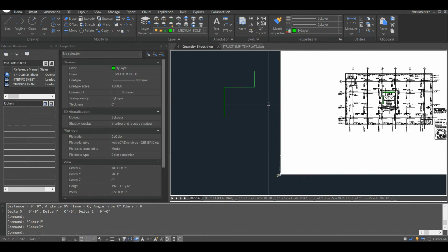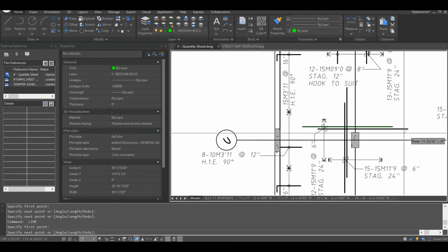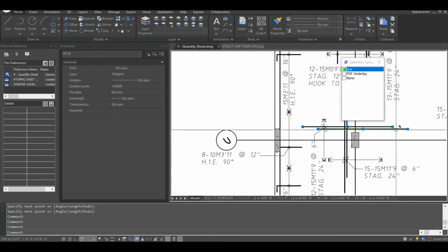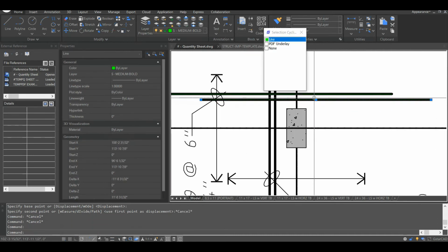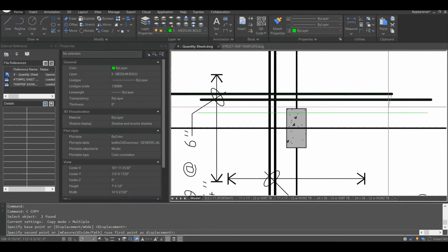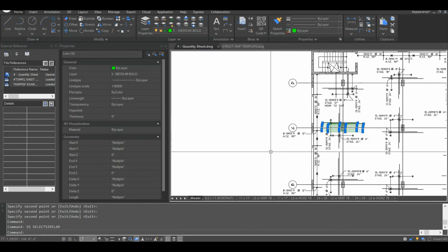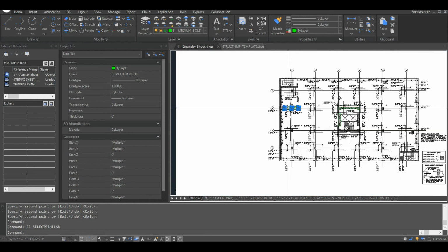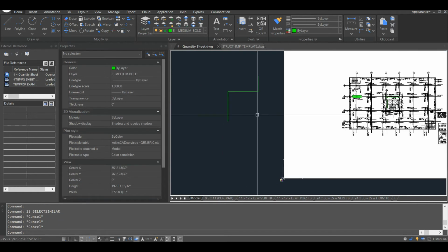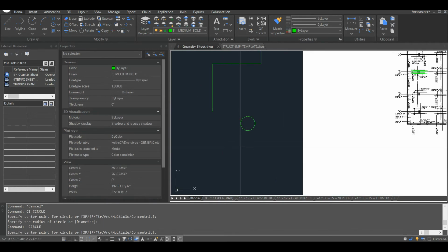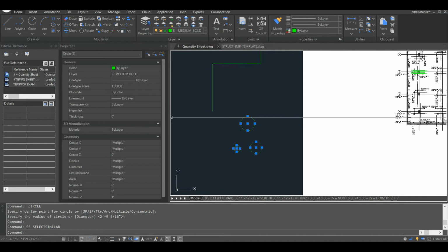So the last little thing I'll show you here is that you see I got all these rebars here, right? If I actually took the time to draw this mat as it would look in real life, let's say I space these, I could just do an array, right? But I can use something called select similar. I have a command set for the SS, and you can get every line on that layer. And if I had a Lisp routine or something, I could use that to get all the lengths all at once, right? So you can do that with anything, with circles, with blocks. If you have a certain type of block and you do the select similar, it'll select all those blocks. They give you the quantity of them.